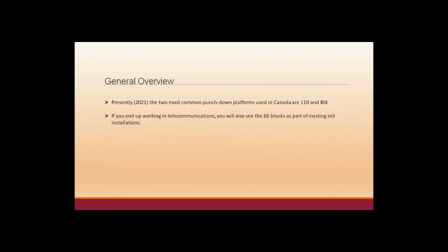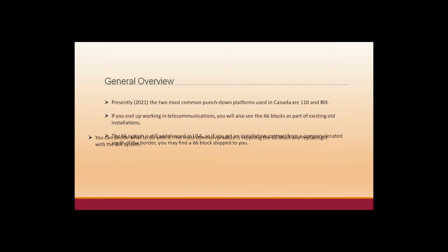If you end up working in telecommunications, you will also see 66 blocks as part of existing or old installations. The 66 system is still widely used in the USA, so if you get an installation contract from a company located south of the border, you may find a 66 termination strip or block shipped to you as part of the installation equipment.